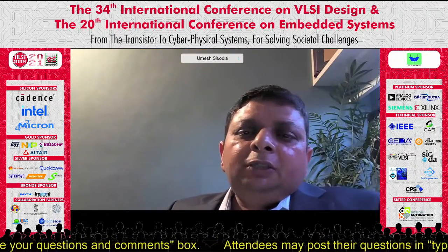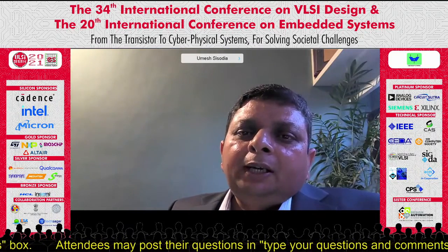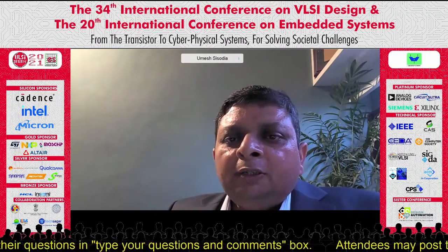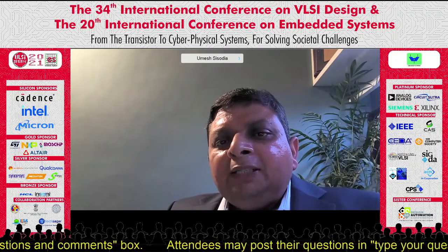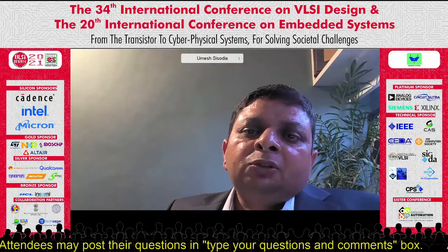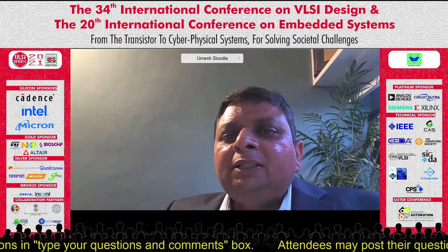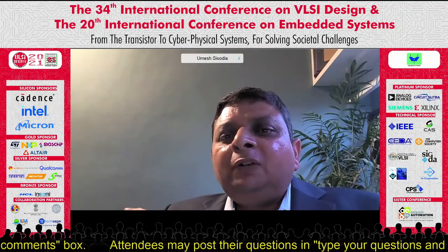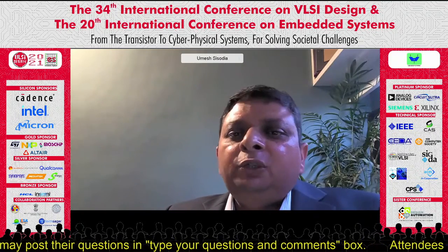Yeah, this is one benefit actually for HLS, that when you are designing in a high-level language, at that time you don't have to worry much about the underlying technology nodes. In fact, at Circuit Sutra, what we have realized is that HLS has to be done by two sets of people. One set, the software programmers, who will write the code which is synthesizable, and the other set has to be the RTL expert who will use the right set of configuration parameters and the right set of tool features to get the RTL which is fully suitable for their requirement.